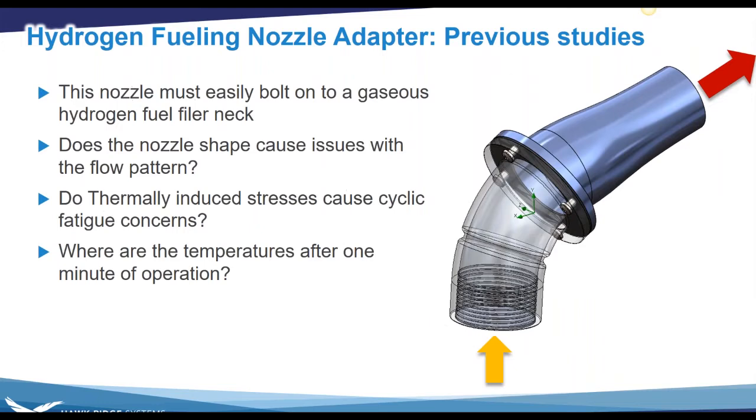So once we looked at the flow characteristics based on shape, and we took a look at how we can assess thermal stresses and cyclic fatigue in SOLIDWORKS Simulation, in this next step, we want to go up to looking at bolt preloads, solving for some complex contact, and going through a couple scenarios that induce quite a bit of plasticity, where we can get a look at whether or not our gasket stays fully in compression and whether we think we still have a good seal. So this next one will be a bit of a step up in terms of the complexity on the structural side.